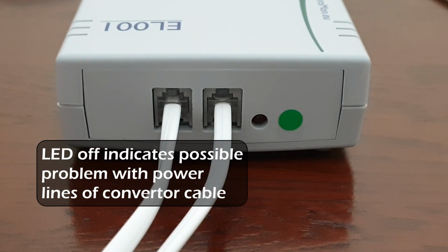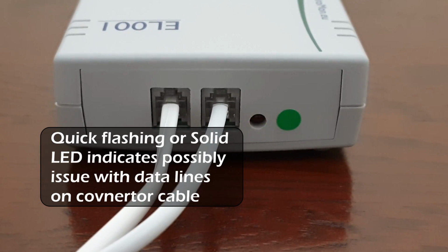Now, if the LED is off, then most likely there's a problem with the power lines on the converter cable. And if the LED is flashing very quickly or solid, there could be a problem with the data lines on the converter cable.